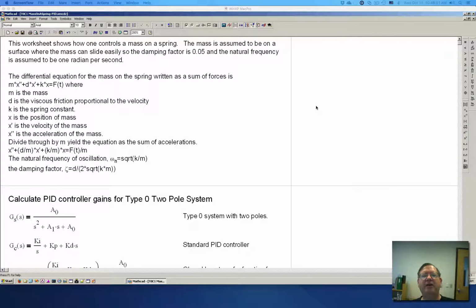First, most of the videos are trying to explain how you can calculate the natural frequency and damping factor from looking at the waveform. And I've seen those videos, and my thoughts are that's not the way you do it, except for maybe to get a rough estimate. If you want to do it correctly, you use system identification, as I have shown in some of my other videos.